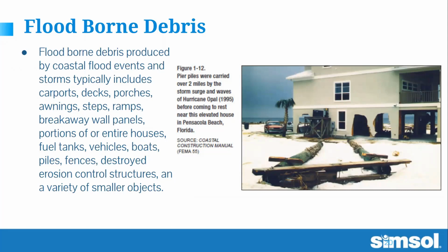The other thing to keep in mind too is don't just look for debris outside the house. In certain parts of the country where basements are prevalent, they have heating oil tanks that are supposed to be strapped down, but not necessarily strapped down well, or if at all. And when the basement fills up, those things can turn into basically fishing bobbers and bounce around, causing all kinds of problems. Also, think about other things in the basement. You're going to have refrigerators floating, washers and dryers, things of that nature. All those things become debris floating around in that isolated part of the basement, and they can knock into interior columns and different things, causing structural damage inside as well as outside of the house.